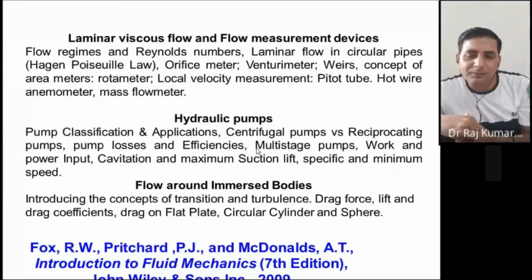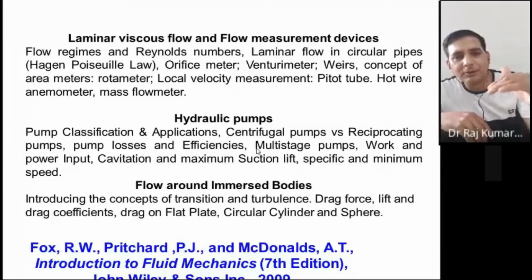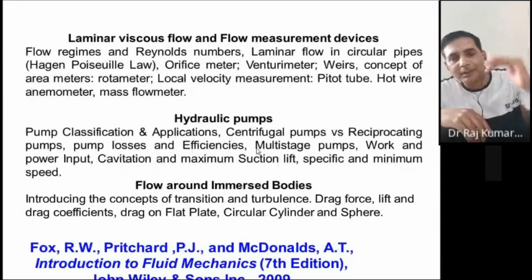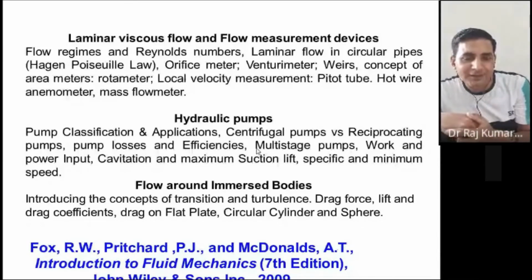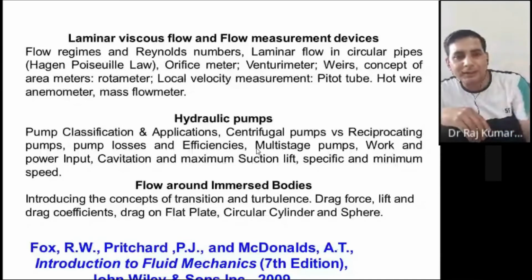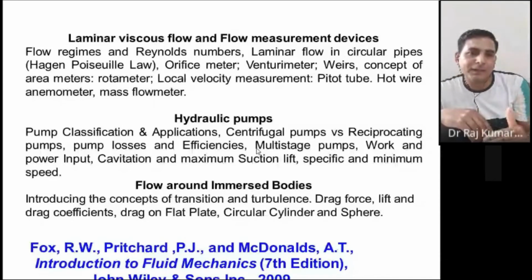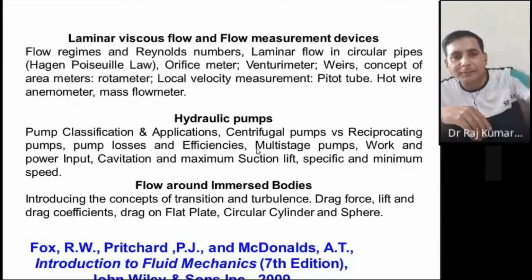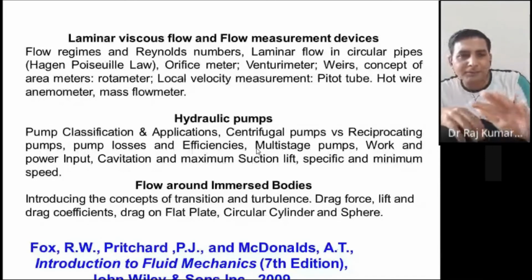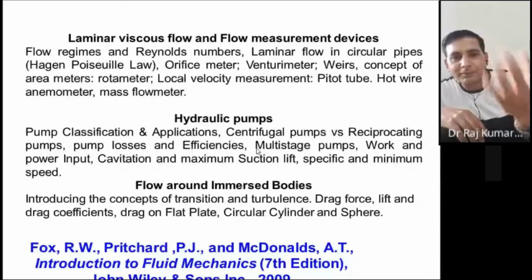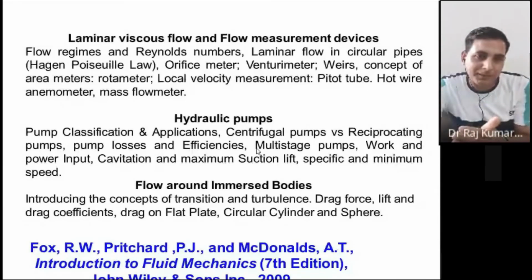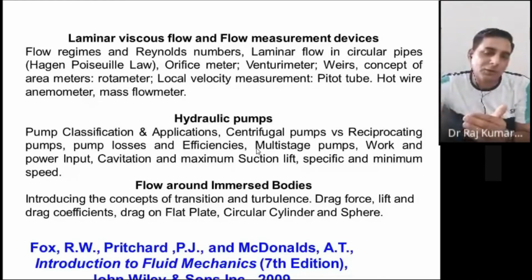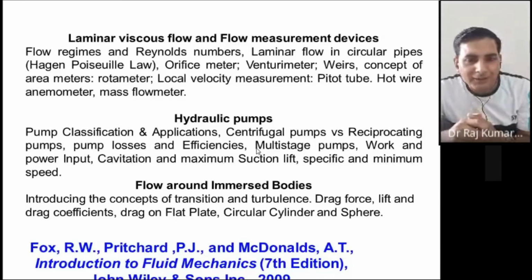Then you have the multi-stage pump, just like for a very tall building. Each pump has its own capacity, just like each person has their own energy or capacity, right? So it cannot work beyond that. Let's say a pump can transport fluid up to 100 meters. After 100 meters, it cannot give any velocity or discharge. So at 100 meters, you have to put one more pump, so that you can transport it to longer distances. Are you getting it or not?